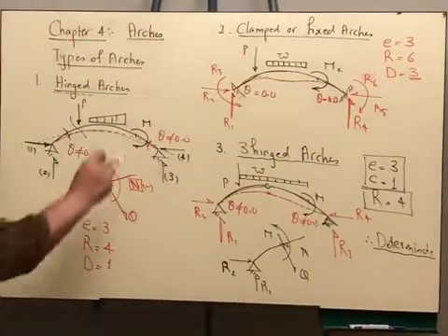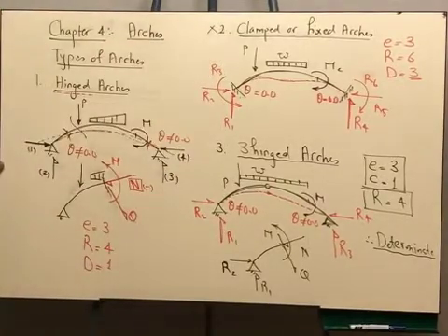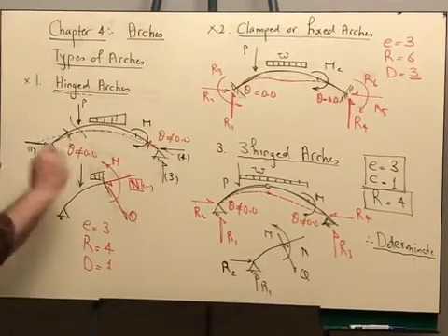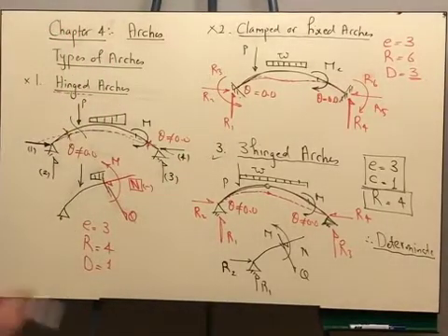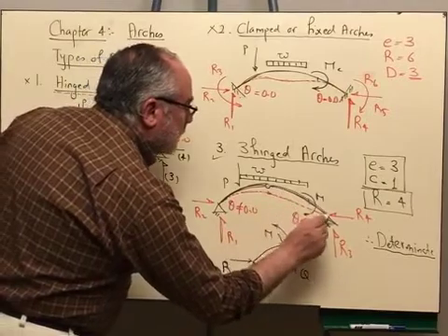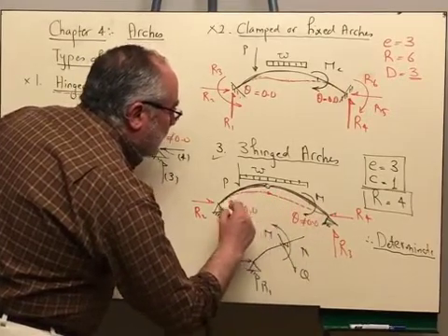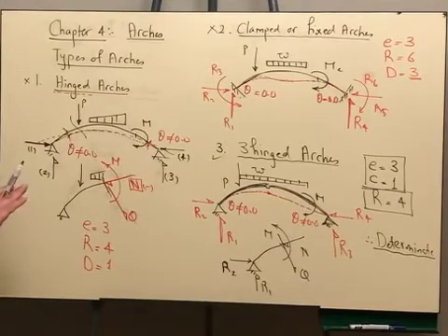This means that I cannot study this in our course because we are only focused on determinate structures, and this one as well, but we can solve 3 hinged arches. So I'm going to explain for you 3 hinged arches. This curve might be a parabola, or it might be a part of a circle. So we are going to see how to solve for the internal forces in this type of arches. So simple, we are just directly applying the equilibrium equations.